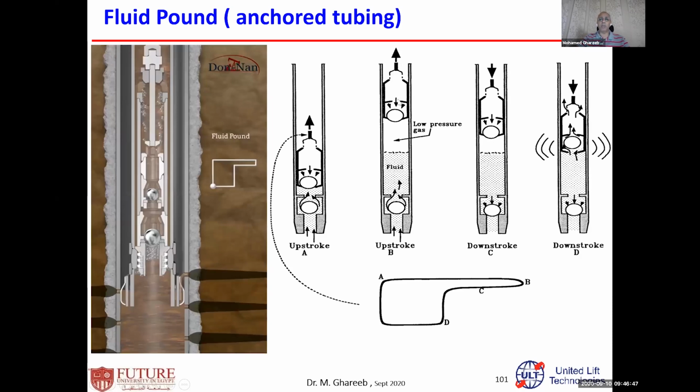Then while we are going down, for the standing valve and the traveling valve, in order to open, the traveling valve must compress the fluid below it. But since there is no fluid, the traveling valve will not compress anything here. Then the traveling valve will still be closed.